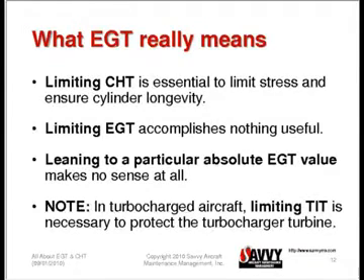The number we really should be looking at is CHT, because that is the closest measure we have of how much stress the engine is under.